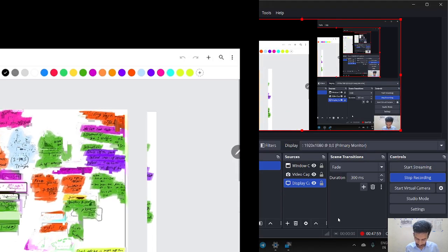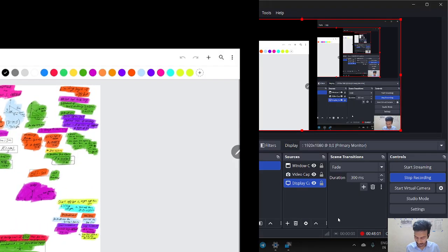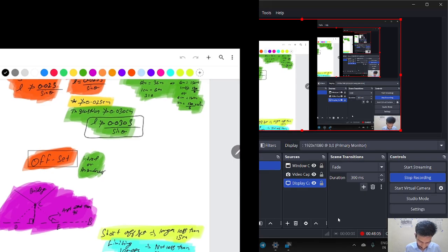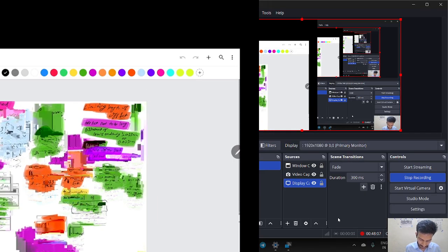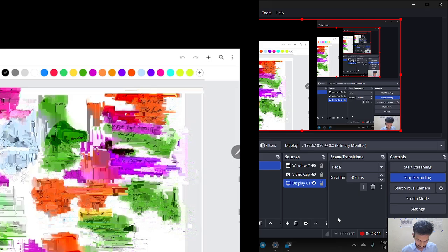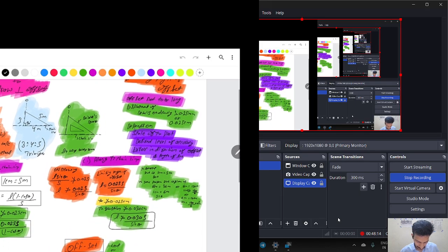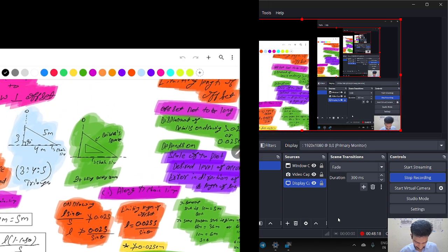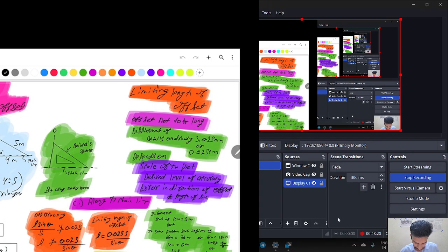Now, the topic is offset. What is offset? A lateral or perpendicular, as I usually told. Methods to draw a perpendicular offset: there are three methods. First, swing the tape or arc line method. The second is the 3-4-5 triangle method.